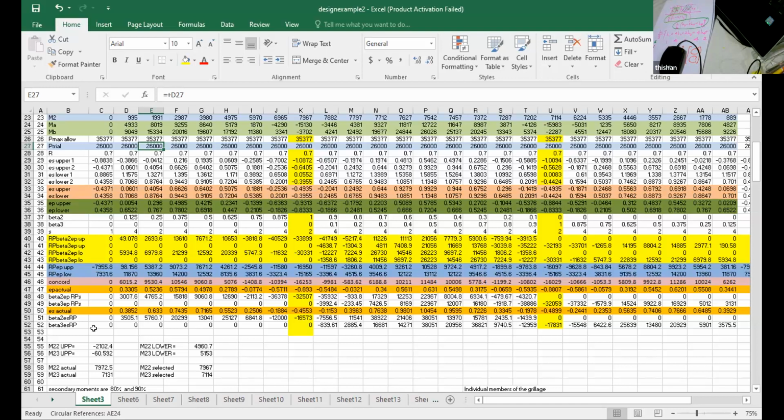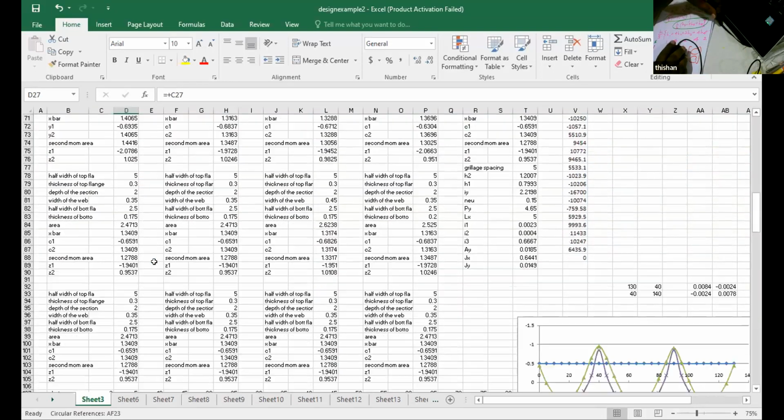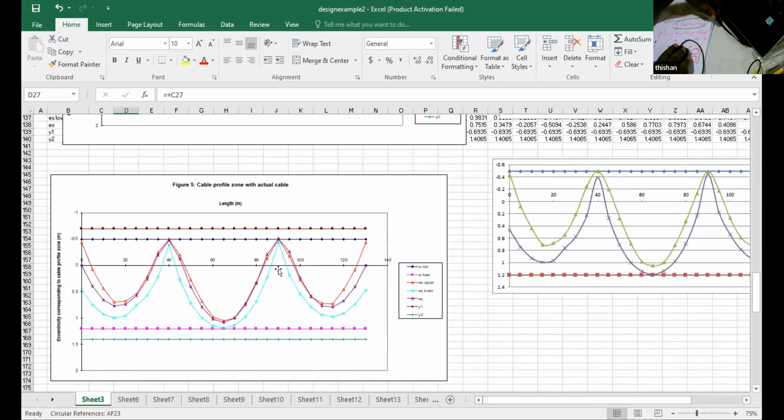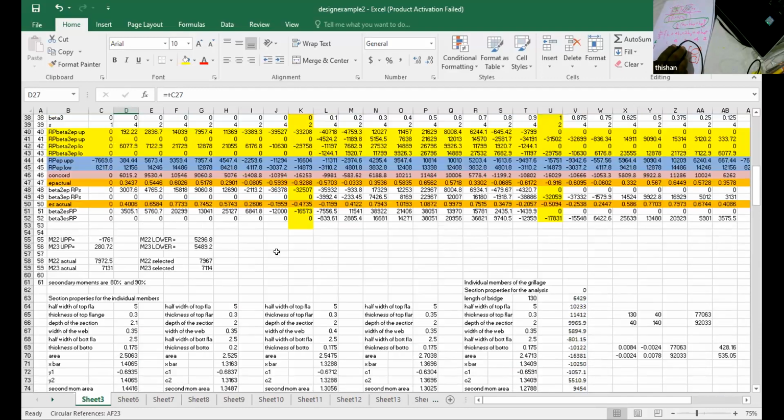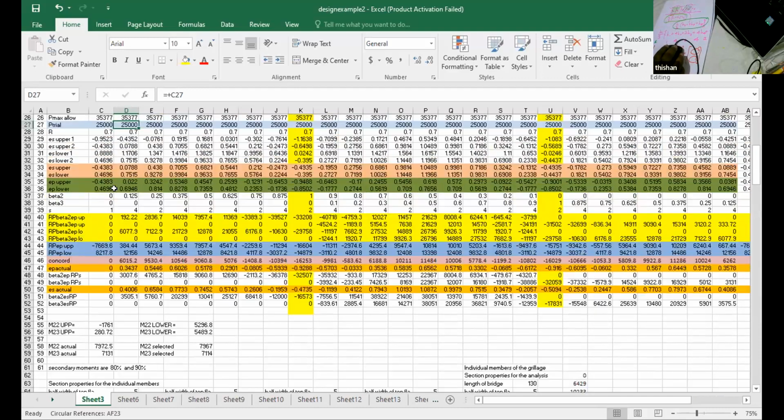So that's why it's very important that we do this particular check when you are doing a design, because the force of 25,000 actually shows that it's perfectly okay with the profile, perfectly okay, except here it's also marginal, but it's adequate. But there's no answer. There's no answer. The moment you come to 26,000, there are plenty of answers. So you can select the pre-stressing force.